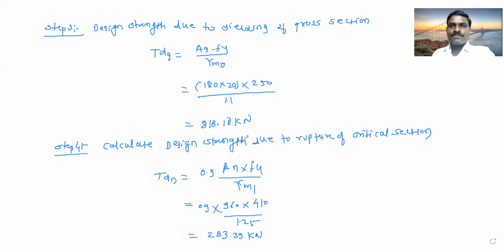Okay, so always do not calculate block shear strength for the plate. If an angle section or any channel section is there, the thickness may be less. For channel section, flange section, 8 mm, 10 mm thickness are there. So where the thickness of the section is less, there may be chances of block failure. Do you understand what causes block failure? If the thickness is less, what will the bolt do to that plate or that angle or that channel? The bolt will break it. So block shear failure will occur where the thickness of the section is less.